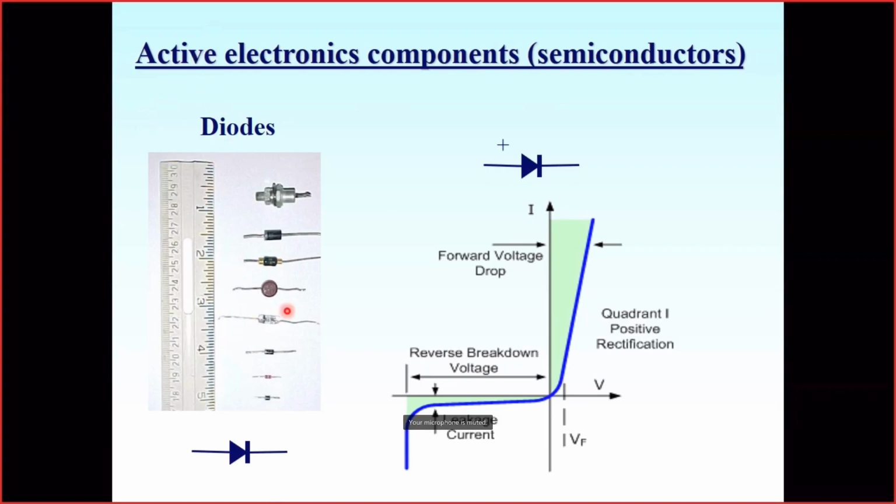You probably should know quite a lot already about diodes. Just remember that the most important feature of the diode is one-direction current transmission. When a so-called forward voltage is applied to the diode, the current through the diode is quite high and nearly not limited. Generally there is some resistance of the PN junction, but it is quite low, so we may have a very high current.